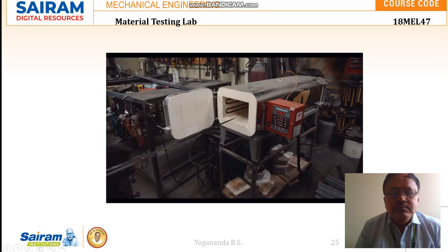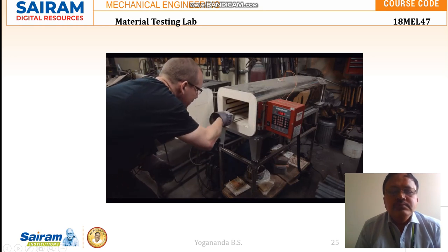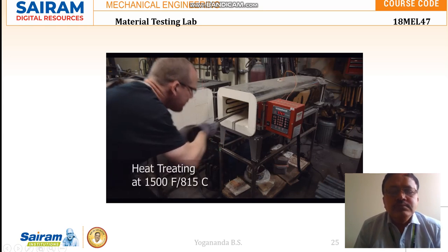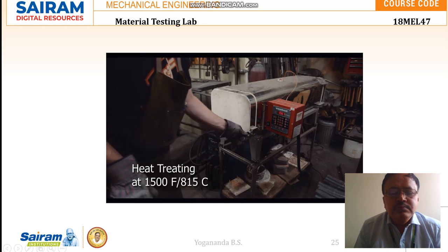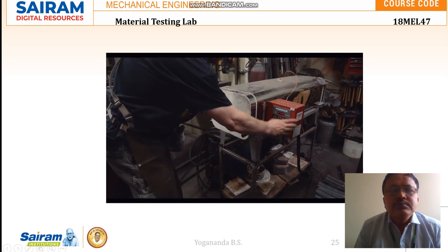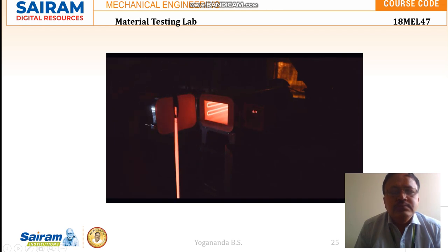Now it's time to heat the blade back up to critical temperature and then quench it quickly in a high-speed quenching oil. The oil will cool the blade down rapidly and cause the austenite to convert to the hard martensite. When quenching in oil, I always wear full face protection. If the oil gets too hot, it can rapidly ignite and flames can spurt up into your face. Before quenching the blade, I quickly check it with a magnet to verify that it is no longer magnetic.